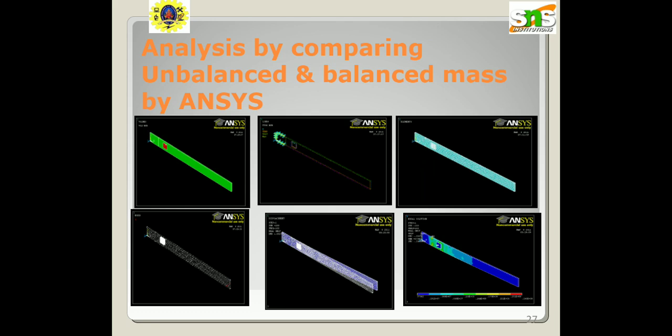And the next one is the tuned mass damper, introduced as a part of the suspension system by Renault Nissan. In the production of car companies, tuned mass dampers are widely used in the crankshaft pulley to control torsion vibration, and more rarely the bending modes of the crankshaft. They are also used on the driveline for gearwheels and elsewhere. The front wheels of a Citroën 2CV incorporated a tuned mass damper of very similar design to that used in Renault.